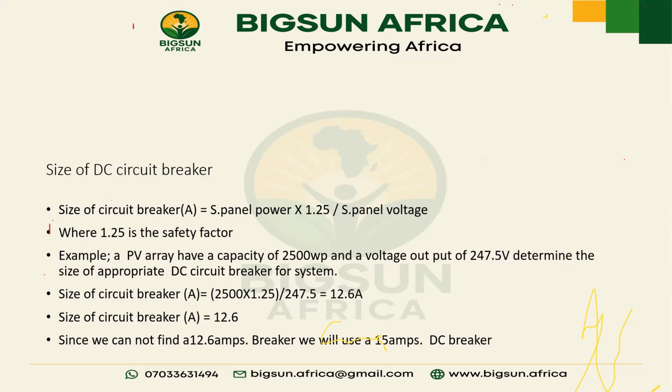So how do we know this before we get to site? You don't know the VOC of the panel. When you are sourcing for your panels in your design, you should know that I'm working with 560 watts. You should be able to see the VOC now. Most of these panels, aside from exhausted ones, used to have a 60 VOC.